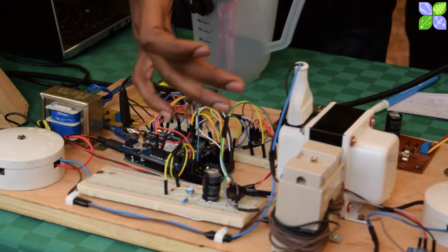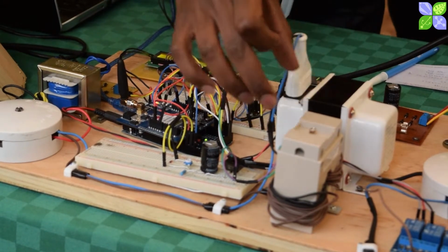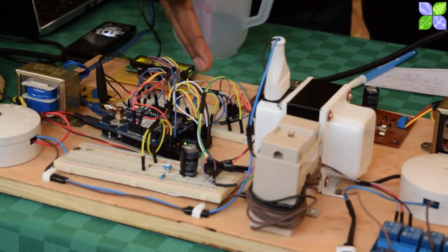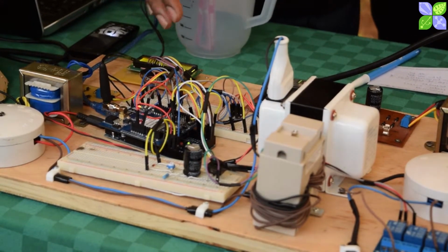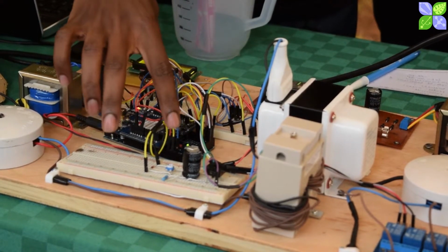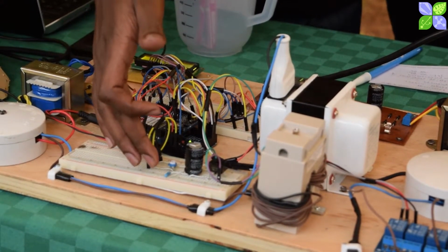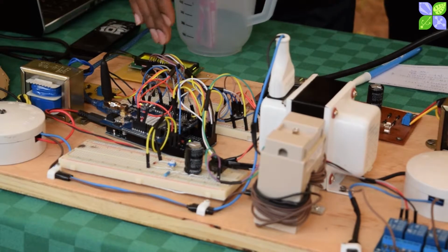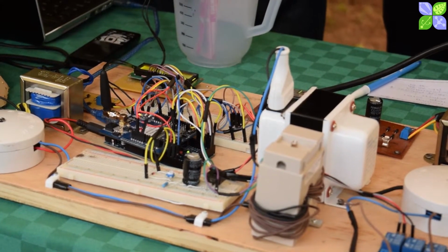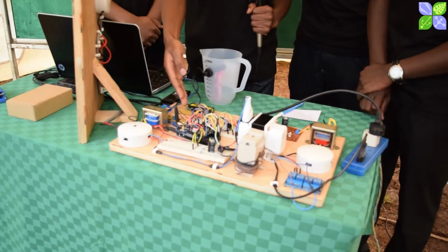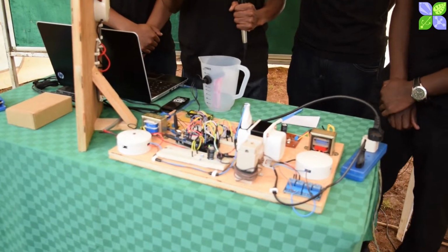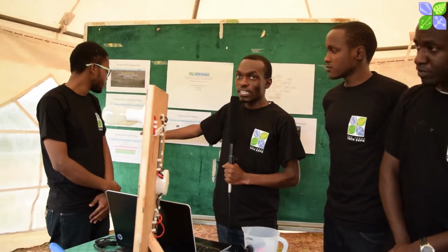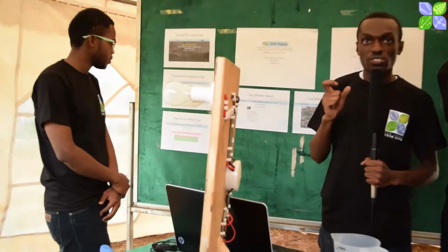There's also a current sensor which has a current transformer, and there is a circuit composed of a rectification, that is a full bridge rectification circuit. Then we have a capacitor for smoothing, and there is a resistor and a diode. All this data is fed onto our microcontroller board, which converts it from analog to digital. Then the GSM shield sends that data wirelessly to our remote control center, where it can be seen using the web application by the monitoring people at the control center.